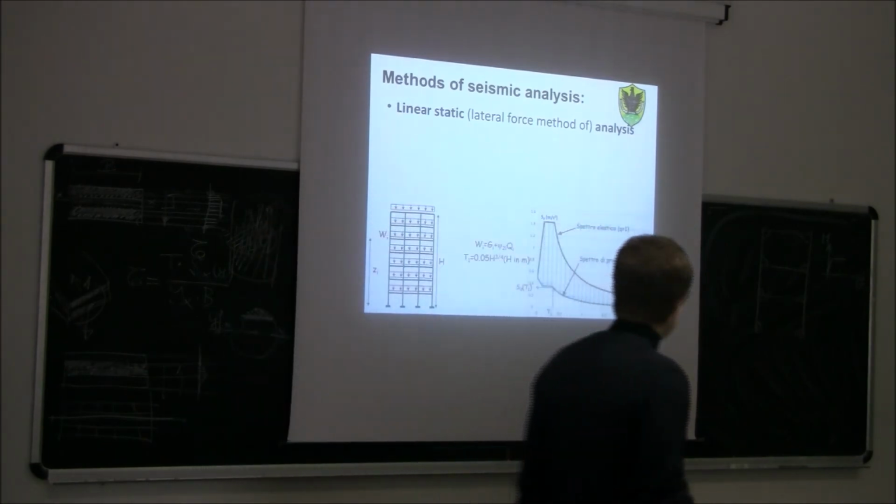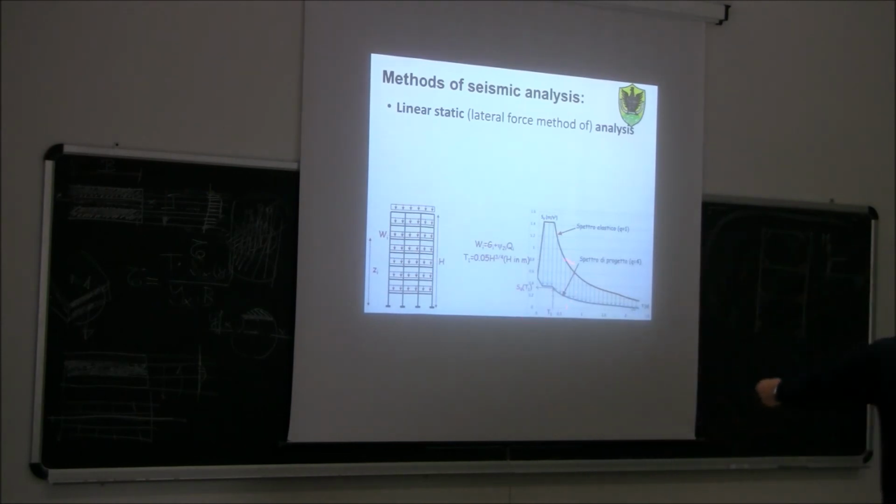We enter into this diagram and we find out Sd, the ordinate of the design spectrum, which will provide us with a value of the acceleration of our structure.